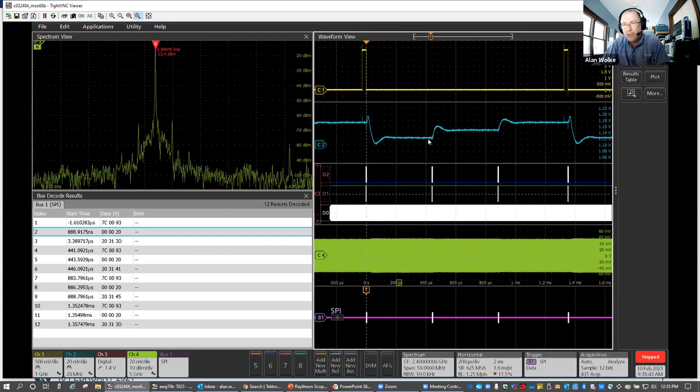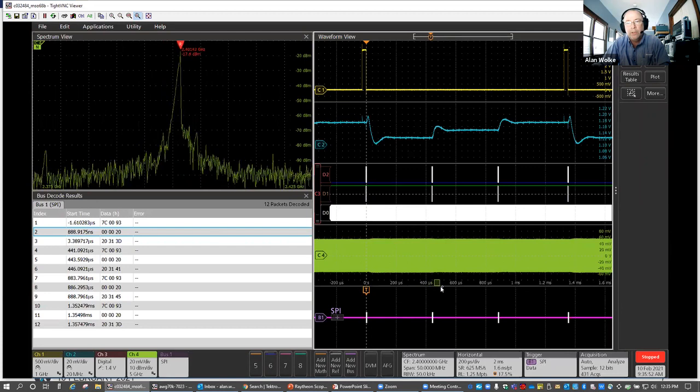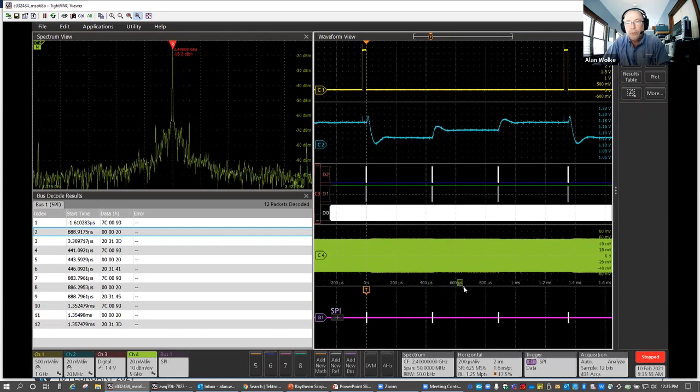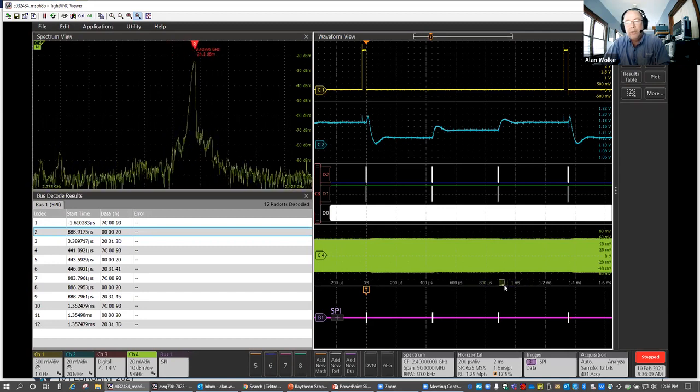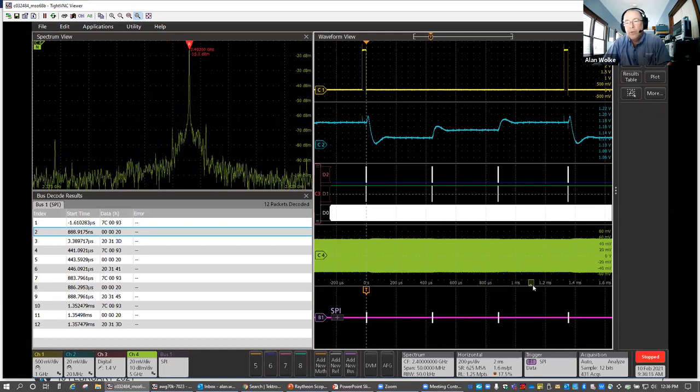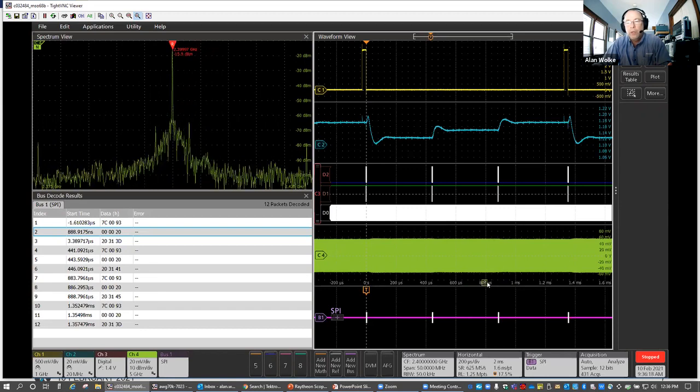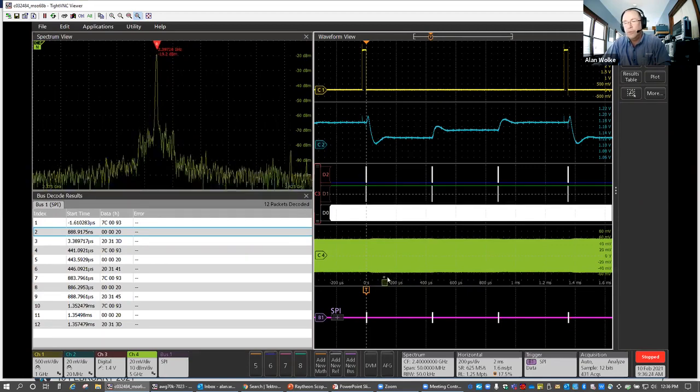And if I keep advancing forward in time, the next place we tune to, we can see the spectral content of that signal move, centered right around that 2.4 gig, right in the center. If I keep moving over in time, I tune to the next stage. Because I've got seamless baseband IQ data here, I can, in effect, slide an FFT anywhere within this acquisition to see what that RF activity is doing. This is what I mean by being able to look at the choreography of your analog, digital, and RF signals all at the same time.